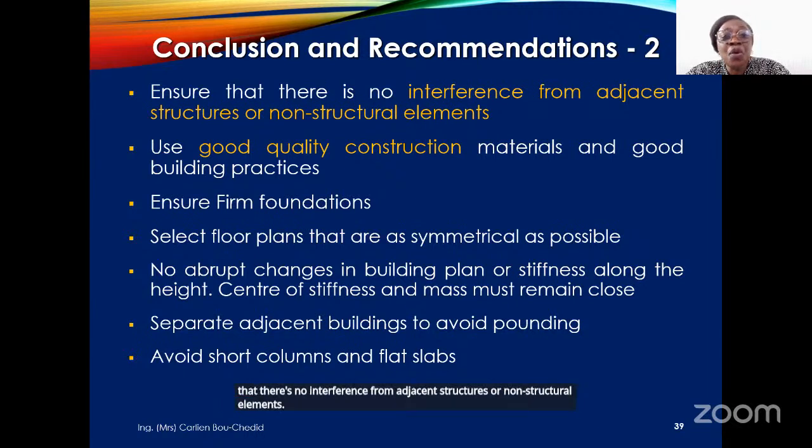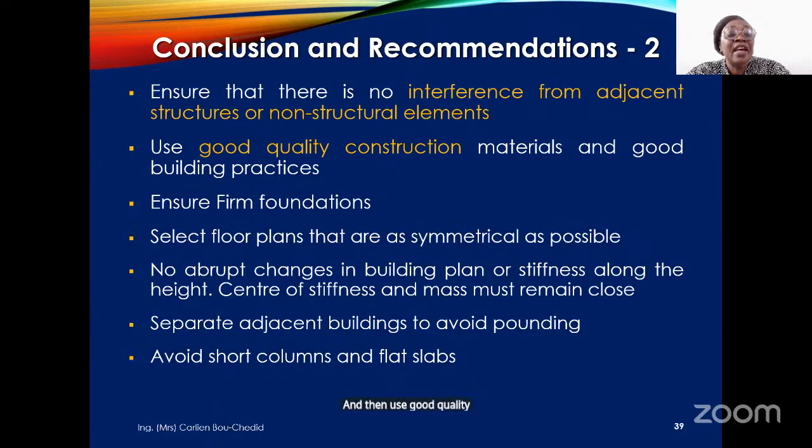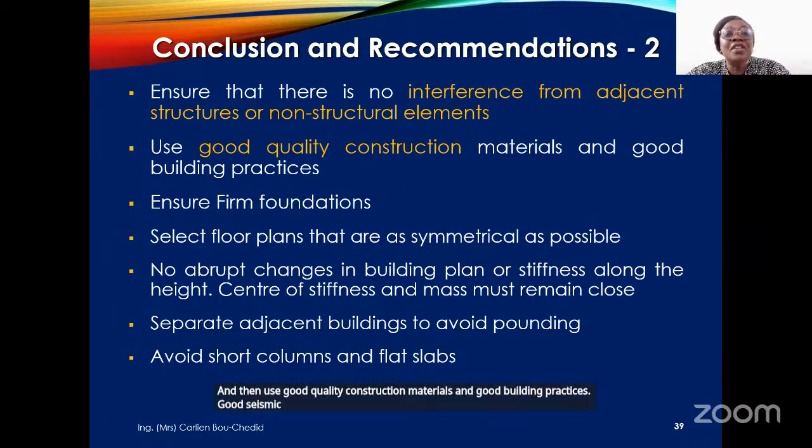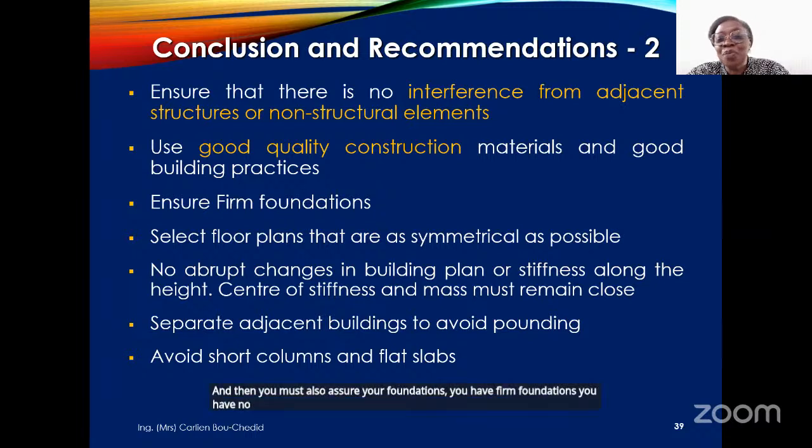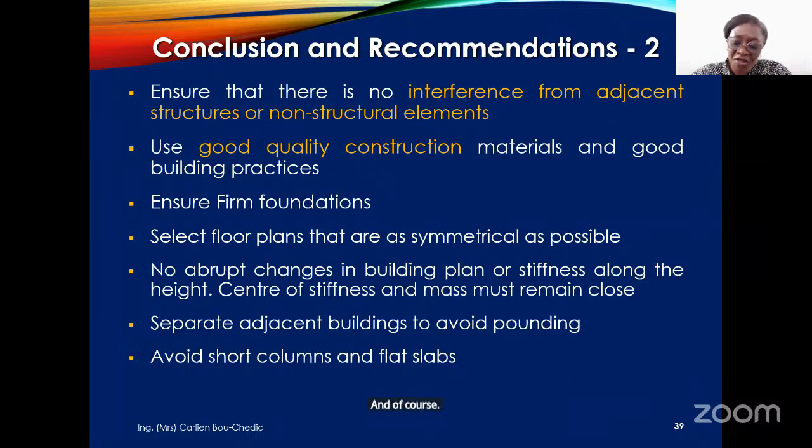And then use good quality construction materials and good building practices. Good seismic design is good construction, good design. So you can't go wrong. And then you must also ensure you have firm foundations, you have no abrupt changes in your building plan or stiffness, and you separate adjacent buildings so that you avoid pounding. And of course, you should avoid the short columns and flat slabs.